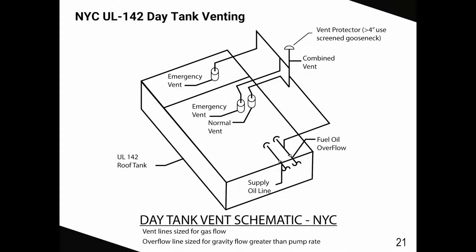So, John, how do we decide that combined emergency vent in there? Well, typically, we'll take the largest emergency vent fitting, which is typically on the rupture basin, and you're going to run that line out into your common. Your combined vent will be the largest fitting size, that diameter of that fitting, and that will be your common combined vent line.